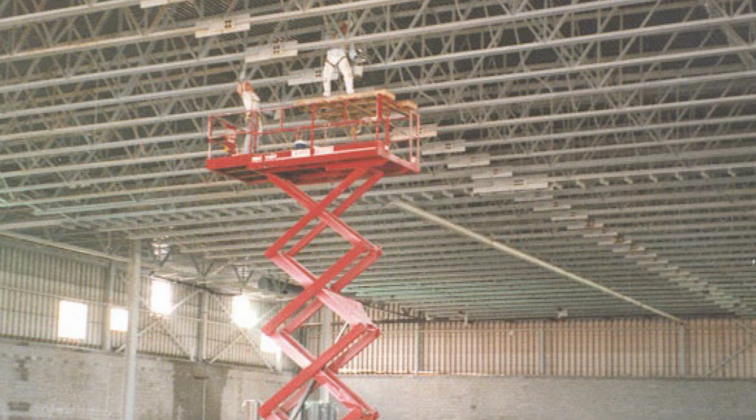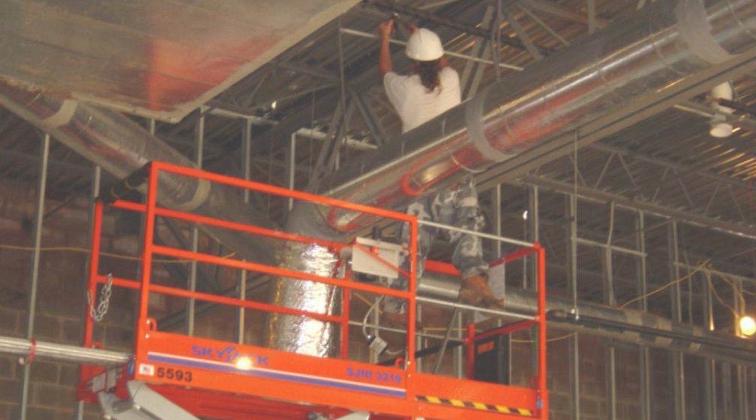Or how about this one? Another issue as far as these scissor lifts, okay, the guy's going up there, well, I need to get higher, what do I do? Well, is he outside the handrails? He needs some type of fall prevention system, which he's got, you know, but is he connected to something that will hold 5,000 pounds? Different story. Don't know. What about this gentleman? Does he need fall prevention? Well, here, what would he tie off to? Did he think about that? Don't know.